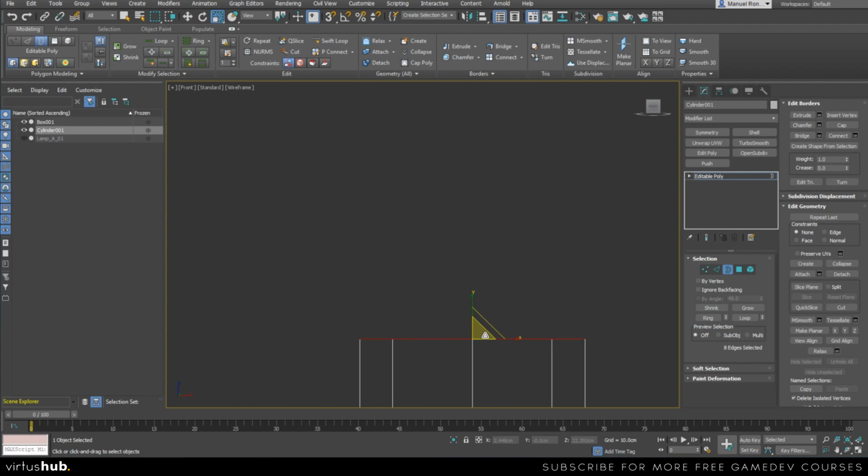Alright, so let's get started with modeling. I'm going to scale from the center, because if I scale from here, I'm only going to scale in the X and Y. If I scale from the center, I'm scaling in all coordinates, so it's a uniform scale. So I'm just going to go like this a little bit. And I'm going to get another piece of geometry by holding Shift and dragging up. I'm just creating new geometry. Okay, maybe I'll lower it a little bit.